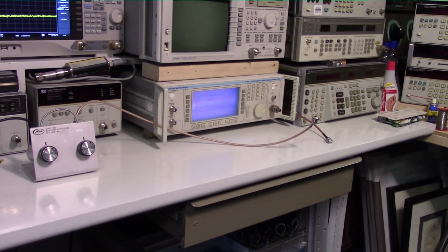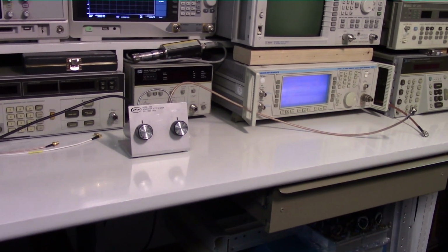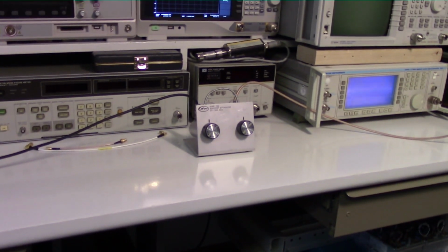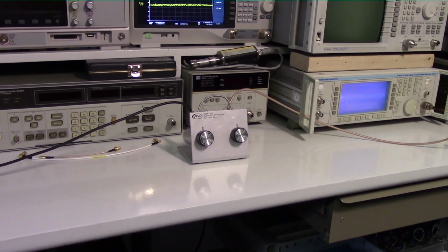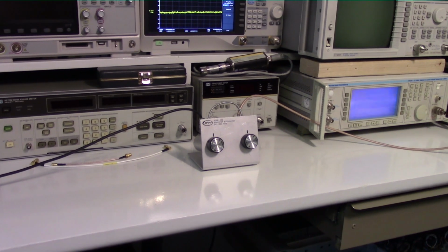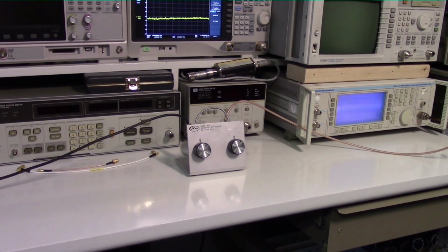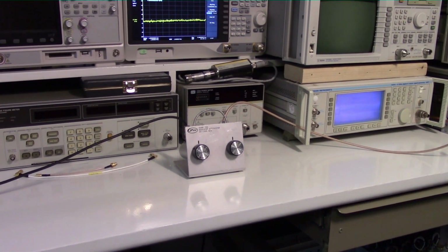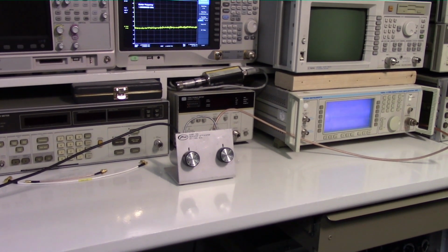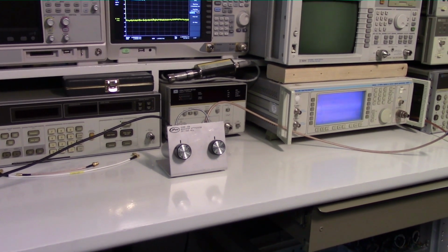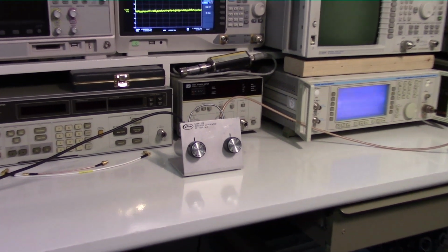So the physical layout of your cables makes a difference. Lay them out in a nice orderly manner where one is not near the other. That'll make a difference. And don't skimp. Don't use cheap shielded coaxial cables. What I could actually do, and I may do this, let me actually turn this off and I'll show you what happens. I'll quickly illustrate how easy it is to get cross coupling between coaxial cables.